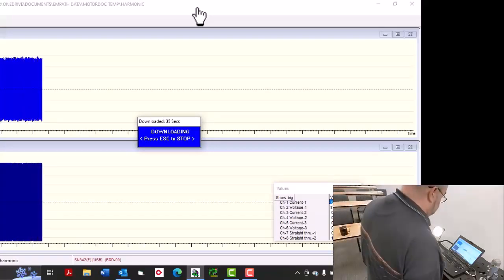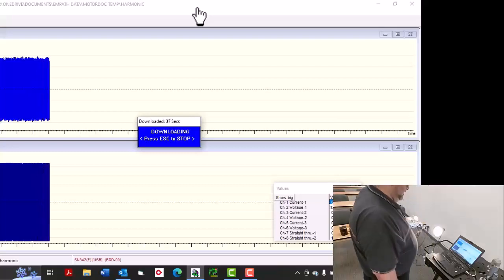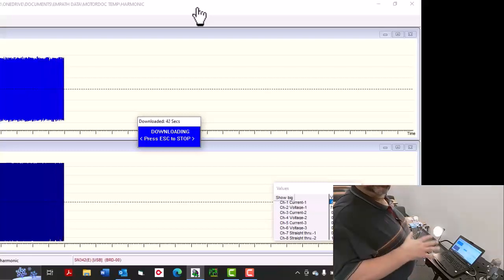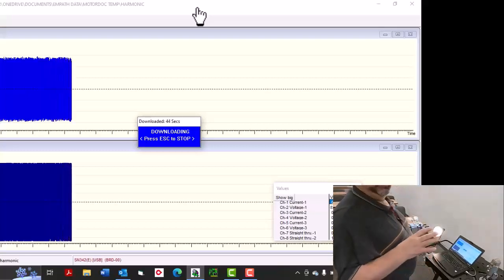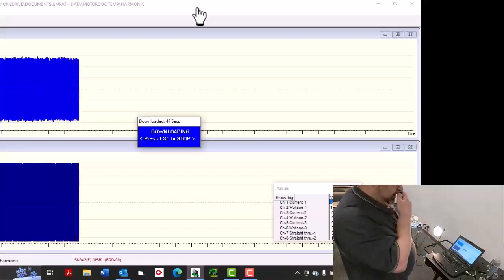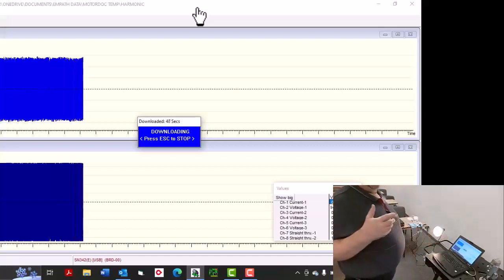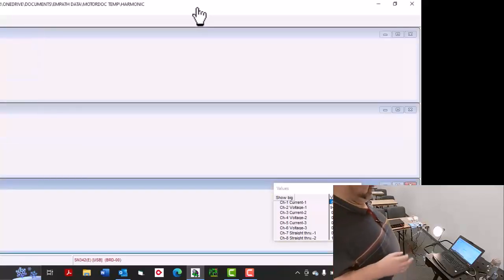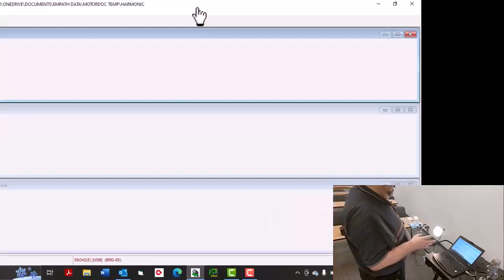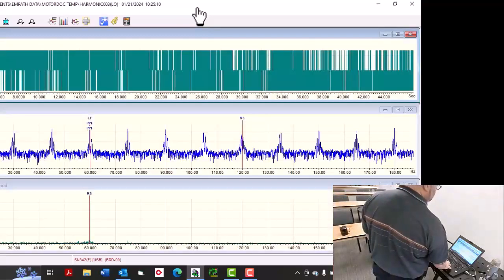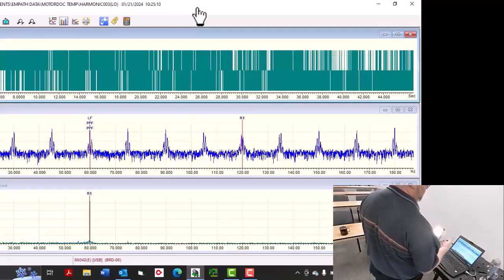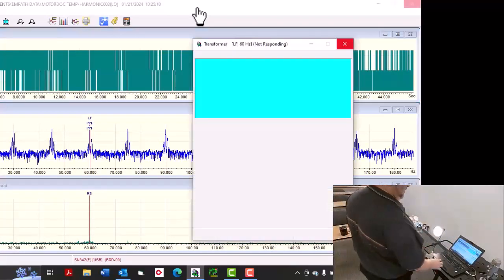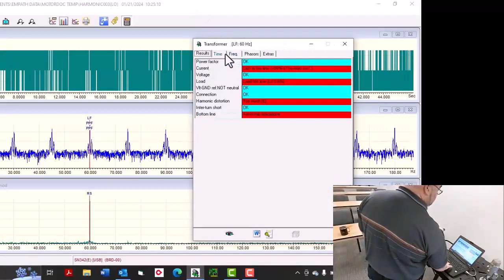Okay, this is telling me very, very low current. So 0.0 something. So yes, we've reduced the amount of current. We have altered the waveform significantly, which means I'm adding a lot of harmonics into the system. I don't know what those harmonics are. We've taken a look at fifth, we've taken a look at seventh. Now, what do they look like? And third, that exist in the system, which are relatively low. I'm aware of what happens, so we take care of our system. So here we go.